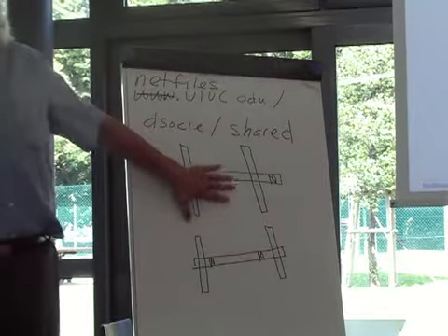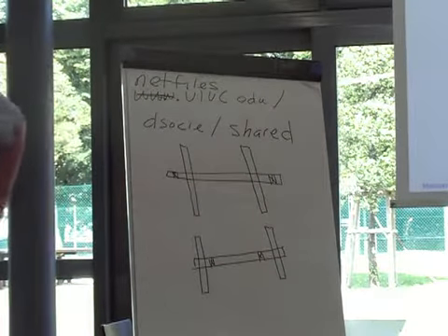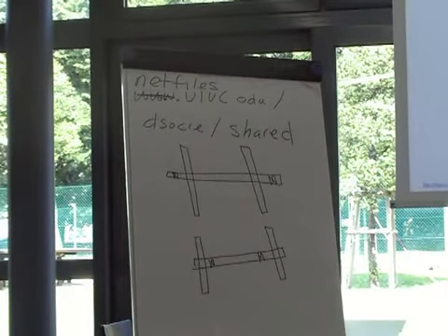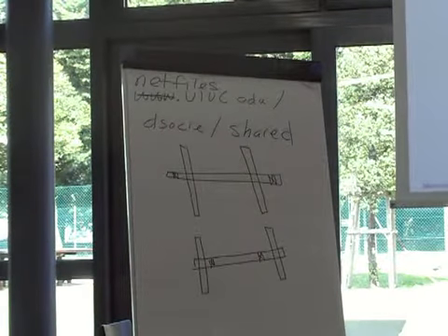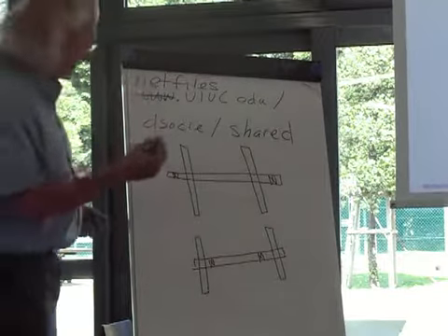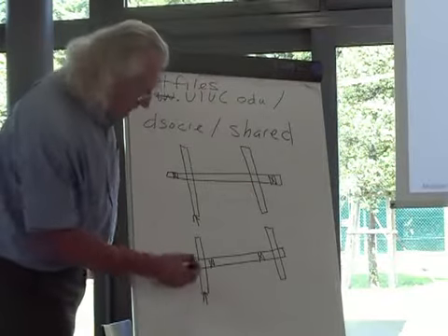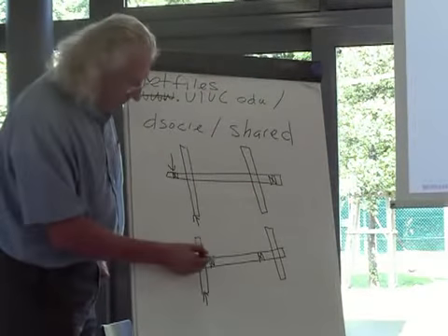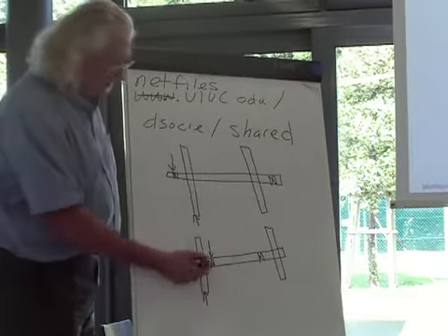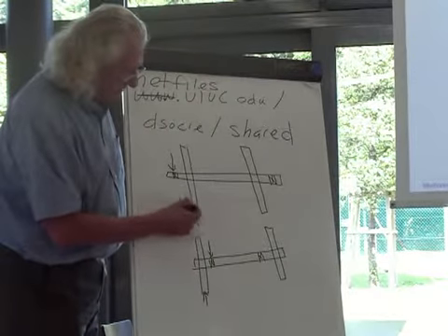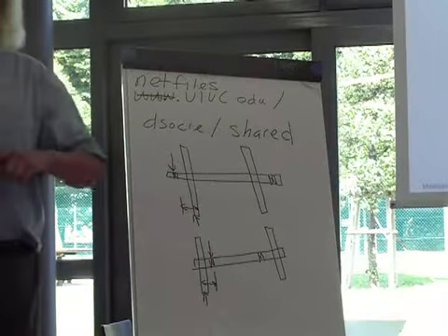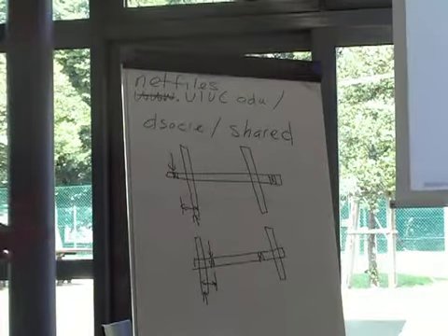All right, what's different about these two from a stress perspective? Yes. Friction is applied to wheels. Yeah. So the reason you're having trouble is you can't find a difference, and that's true. If we look at these two designs, I have the force up on the wheel and the force like that, and here I have a force down from the weight of the vehicle. Then all of the stresses are determined by the bending moment, and the bending moment is determined only by these forces and what the spacing is. So if this spacing is the same, then of course all the stresses are the same, because it's simple bending on both ends of the beam. So there's absolutely no difference.